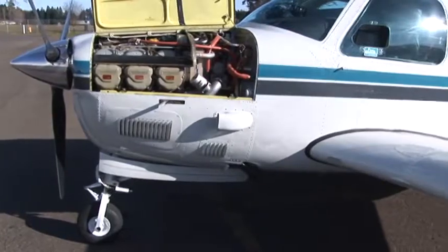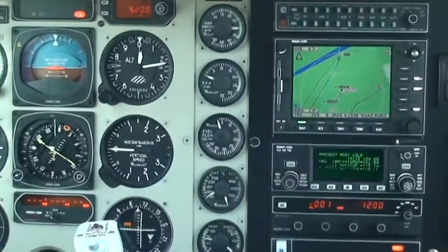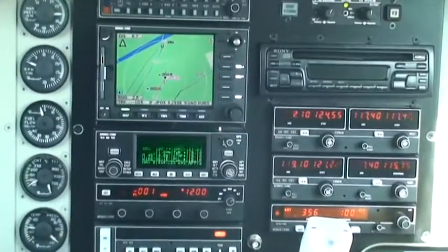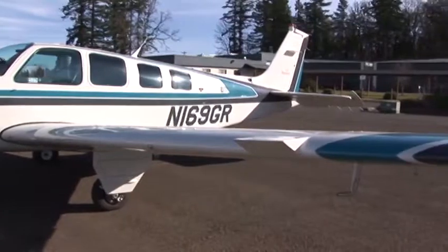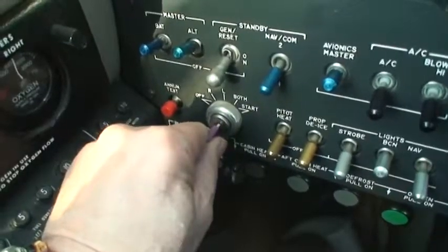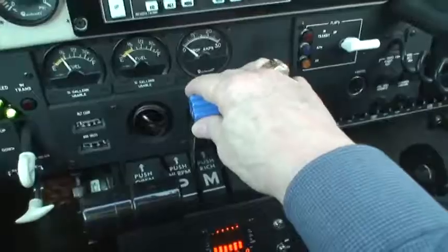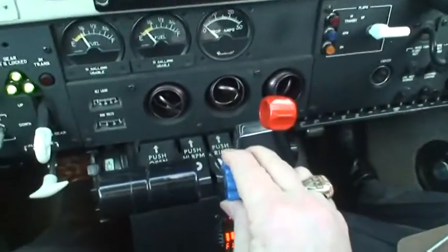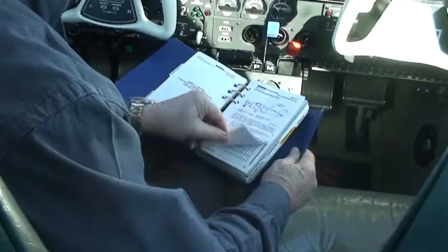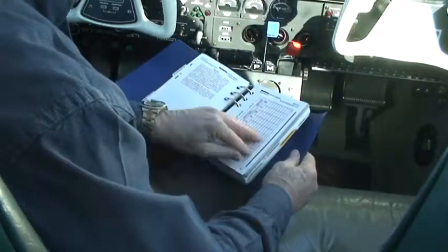There are many moving parts in an airplane, and it is imperative that all systems are functional before flight. Unlike a car, where an engine problem is merely an inconvenience, in an airplane, a sudden engine stoppage or other malfunction can have serious consequences. Therefore, a thorough pre-flight inspection should be completed prior to every flight to ensure the aircraft is prepared for a safe flight. The use of checklists is important to ensure that all necessary flight instruments, systems, and components are checked thoroughly.